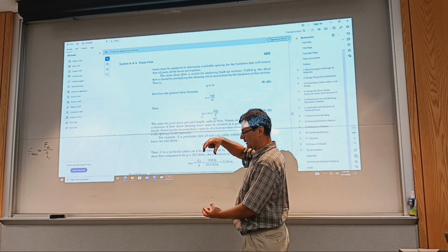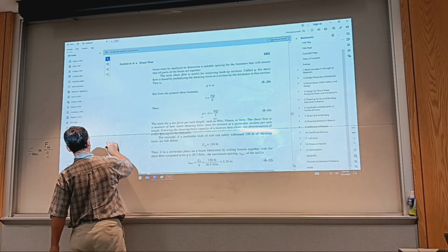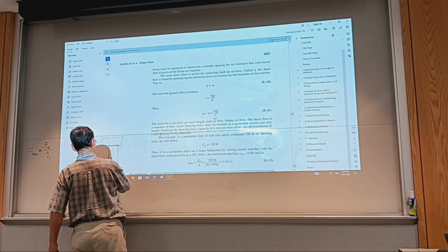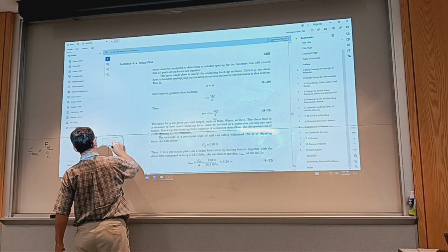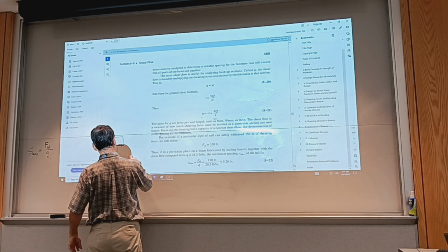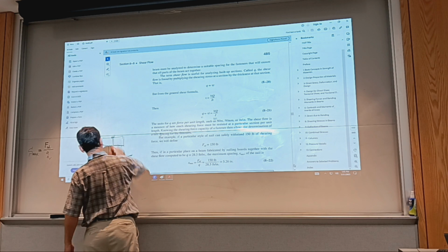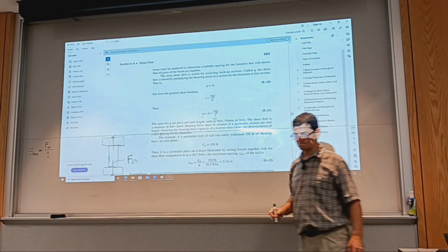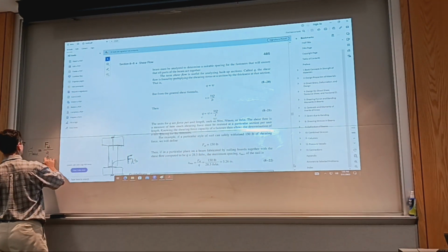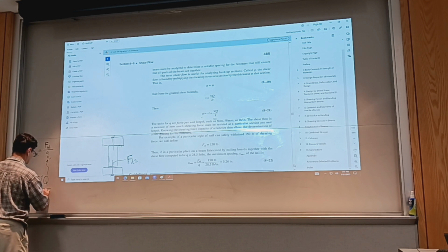So if you have a 2x4 that you make into an I-beam, I'm drawing it in here. If I fabricate an I-beam using three 2x4s, okay, so this is the fastener, and I have F. This is the maximum shear force that one fastener can hold. And again, q is V times first moment of area over moment of inertia.